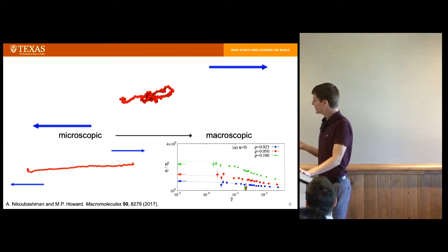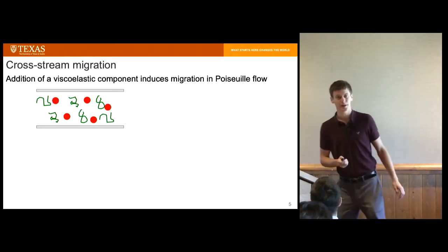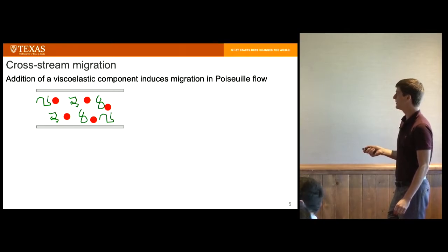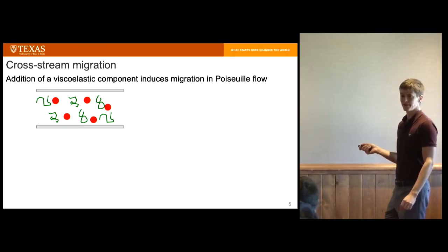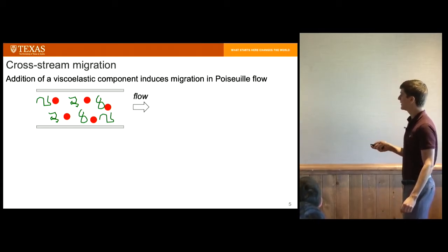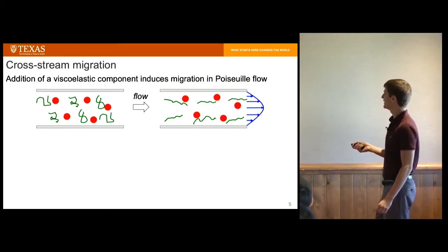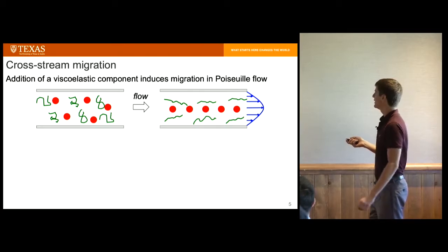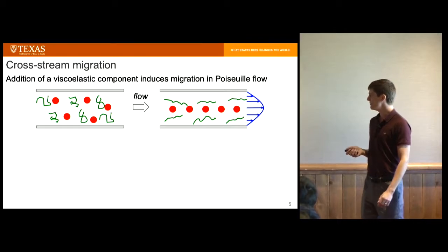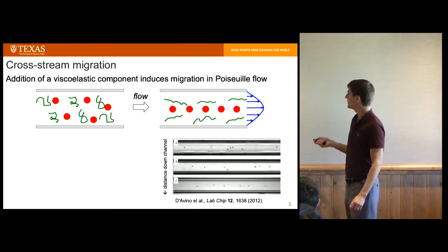One cool thing about these polymer solutions is that they have a property that can help us solve our problem of manipulating droplets. If I take a pinch of polymers and throw them into these particles in a microchannel flow, I want to try to push all the particles down into the center line. What happens is I put it under flow, the polymers deform like they did in the previous video, provided that I'm flowing fast enough, and then the big thing, it turns out, is that the particles can move into the center. And this has been known for about 50 years for things that are millimeter size in diameter, pretty big, or even tens of microns.